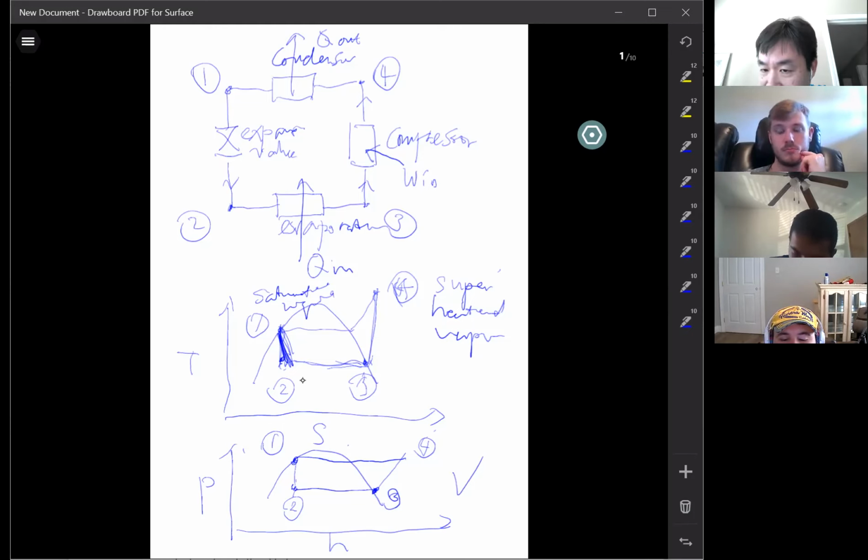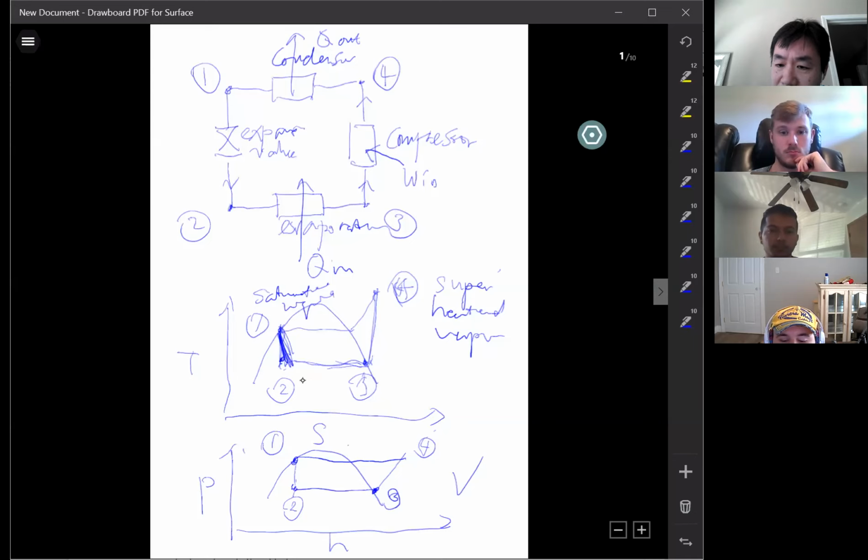Okay, so you will see the video. In the video, you will read the pressure and temperature. You need to calculate the enthalpy. Now the second question here is, I want you to calculate the degree of superheat at point 3, at the evaporator outlet or at the compressor inlet.